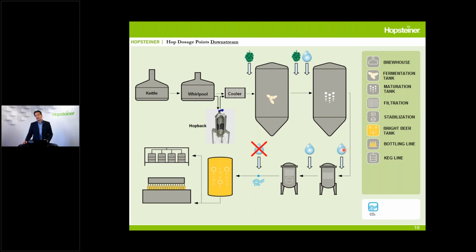That's also something that we can do at the end of the process, before filtration or before the last filtration step that we have. Do not add any downstream products, not only hop oils, do not add any downstream product here behind the last step of filtration, because that can cause problems with homogenization and also with gushing.